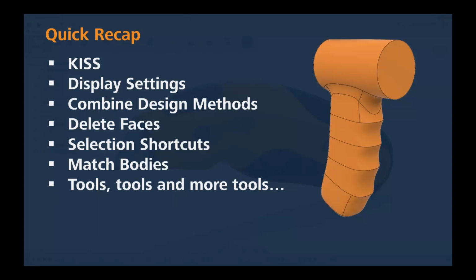Take advantage of the combined design methods, so the ability to use your sculpt, your patch, and your model environments collectively. Deleting faces, whether it be deleting edges, really, is one of the key tools that I just absolutely love about working inside of Fusion 360. Remember your selection shortcuts to help you cut down on the number of picks and clicks that you're making.